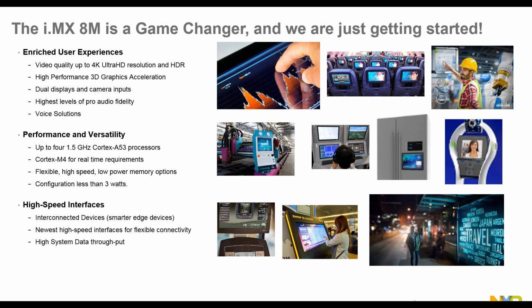The processing capability now with the Cortex A53s and 64-bit cores, and a lot of flexibility in terms of high performance DDR memories that also are low power. And you cannot forget about the high speed interfaces to be connected there. So PCIe, for instance, to connect with Wi-Fi chipsets and allow a great throughput in the Wi-Fi with great range and lower power consumption.